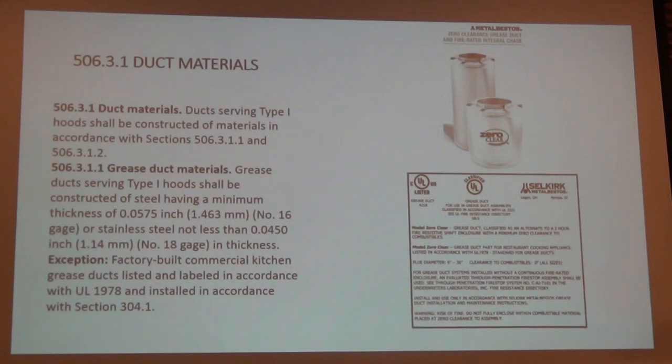So every time we do a hood test, I always make sure that the fusible link is at least a foot or more from the conduit fitting, so that the connector fitting does not prevent the pin from dropping. That's required to be inspected every 6 months, actually by NFPA 96, which they're going to take out in 2018. So there should be special inspections in each city for an inspector to go out to these restaurants every 6 months and make sure they have that tag, that bumper sticker. You are correct. But due to lack of staffing, that doesn't happen sometimes.